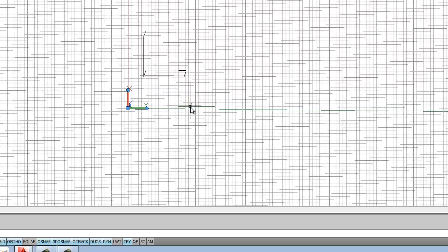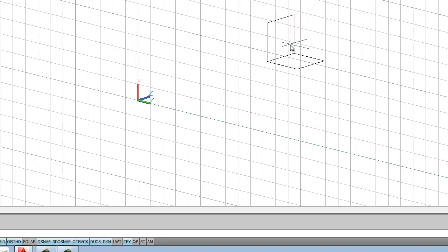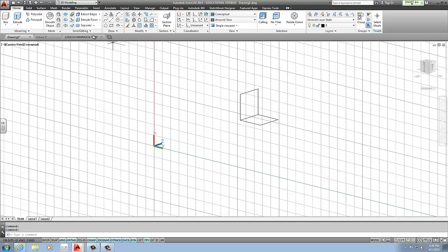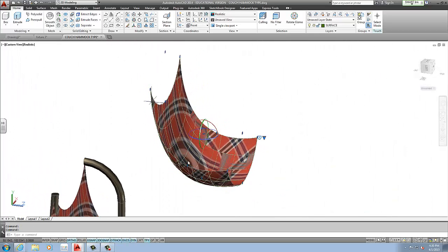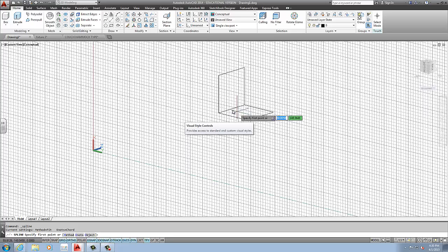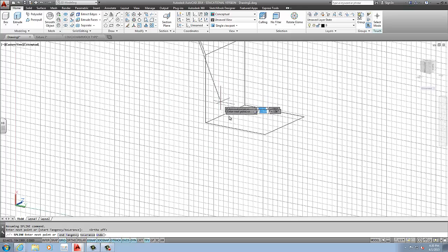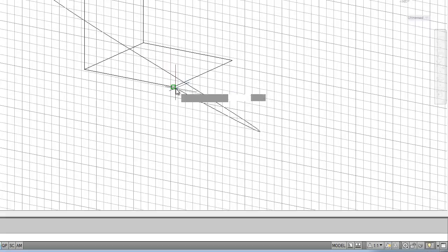So the first one I'm going to do is this side one. This side is going to be this side of our chair. If I go back to my hammock, this would be these 2 points at this edge. To do that, we create a 2D drawing. We use a spline. I prefer a spline. You can use an arc, or whatever you like. I'm going to use a spline because I'm going to make mine a little bit different than what I have in the other drawing. Now, you want to have OSNAP on. Ortho is probably not beneficial at this point, since it's not going to help too much.